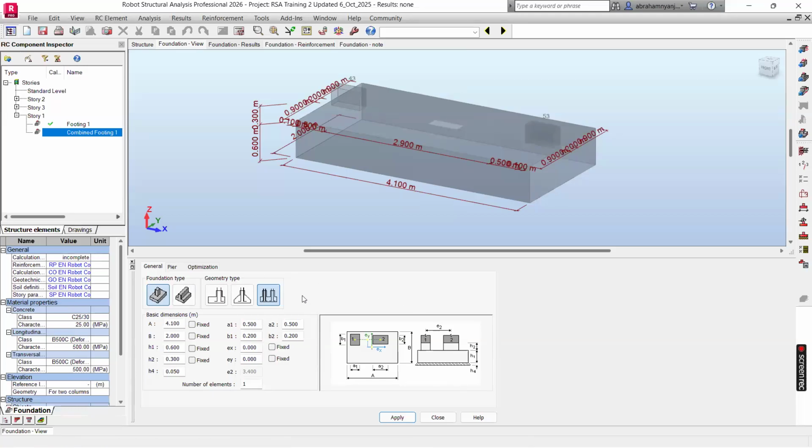We are going to adjust them later on after designing, when we probably find that what we have designed does not display what we want, so we shall adjust it from here. But for now, all these have been set to the parameters we set for foundation, so I'll just hit calculate. Note, make sure you're in foundation view. When you're in structure, you have something else.